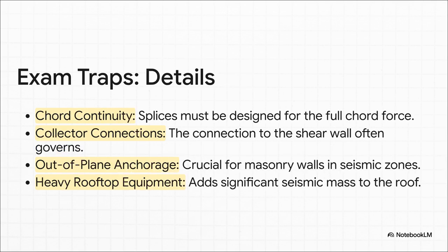And on the PDD side of things, pay super close attention to the details of how everything connects. The exam loves testing chord continuity. Remember, those chords are taking tension and compression, so they have to be continuous. And any splice has to be just as strong as the chord itself. The connection of the collector to the shear wall, that is a classic weak point. And anchoring a diaphragm to a masonry wall is a favorite topic. Oh, and don't forget that big, heavy equipment on the roof adds a ton of mass that the diaphragm has to deal with in an earthquake.